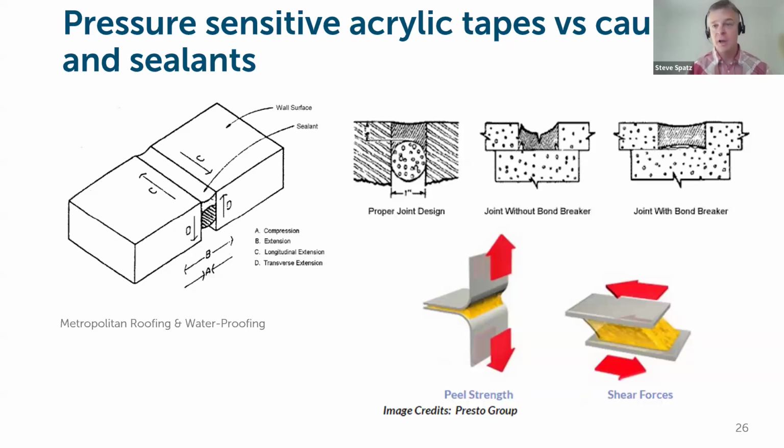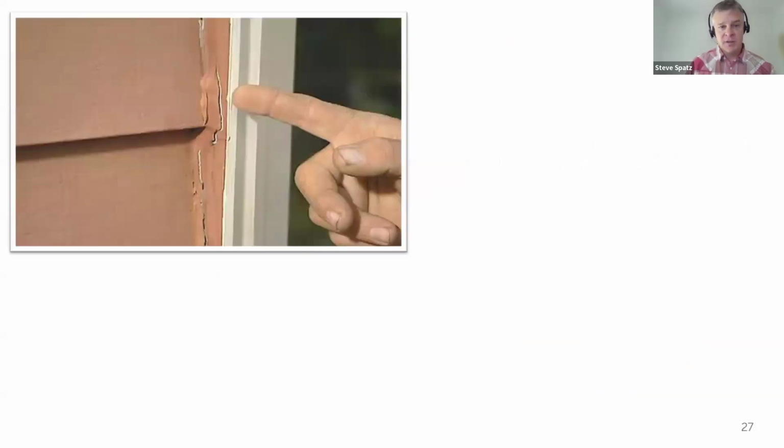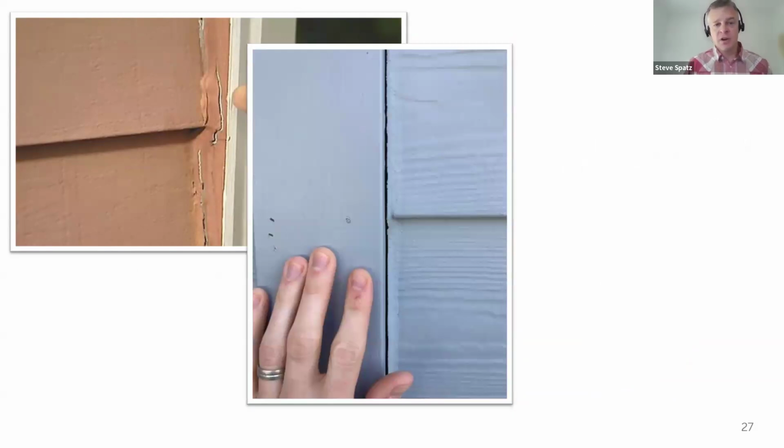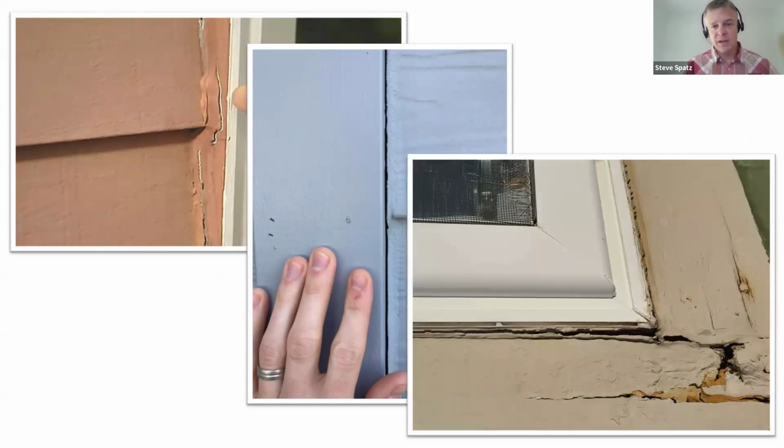Air moves through it. And not just air moves through it, but if you're using caulking at the exterior, that movement of the caulk and the breaking of the bond in those joints creates the opportunity for trapping and capturing water into these sorts of gaps, which inevitably will break down the materials behind it and keep water in rather than keep water out.